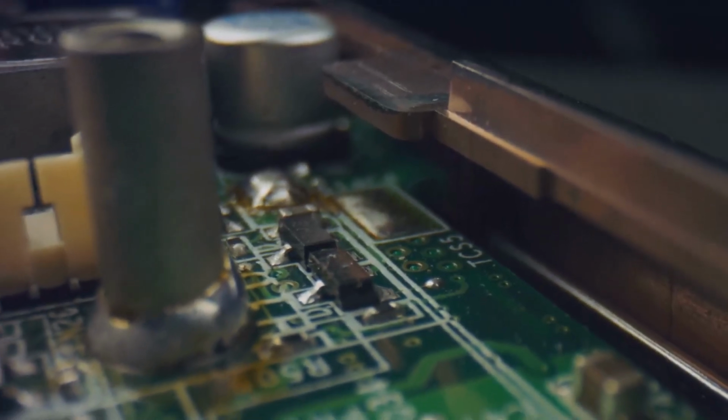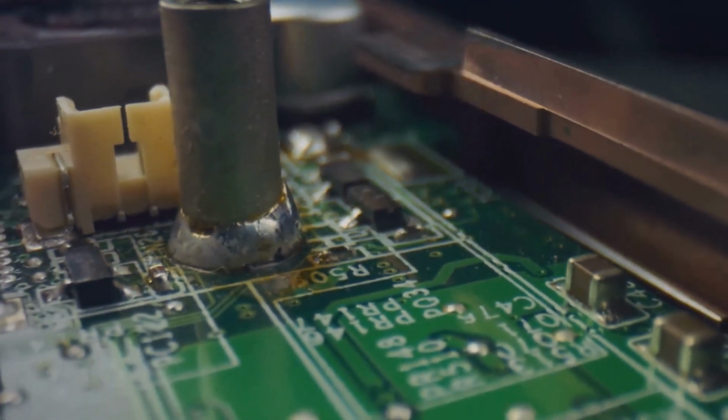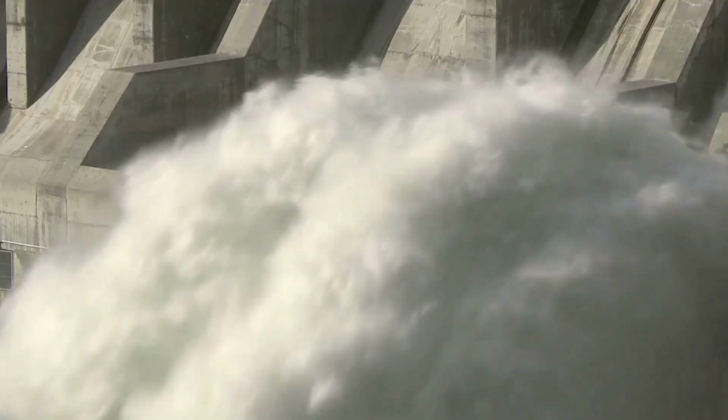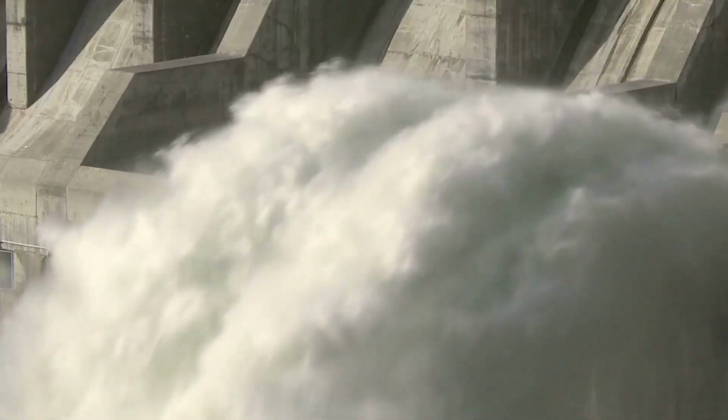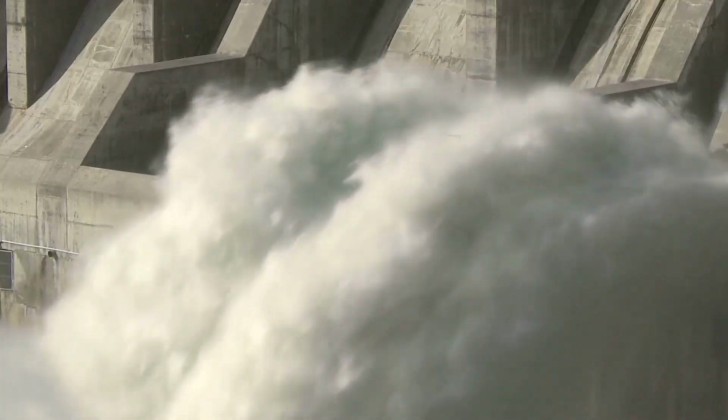While the output is still a series of pulses, these pulses are now twice as frequent, filling in the gaps that the half-wave rectifier left behind. This makes it much easier to smooth out the final DC signal. We can add another component, a capacitor, which acts like a small temporary water tank. It stores energy during the peaks of the pulses and releases it during the valleys, smoothing out the flow into a much steadier stream of DC power that our electronics can happily use.